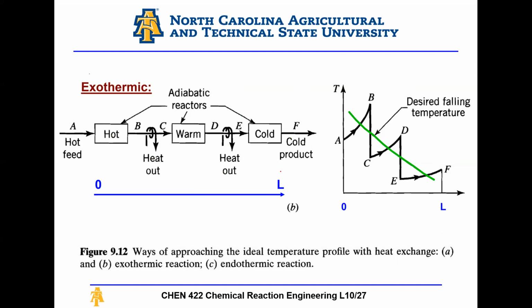A lot of the time you want to do this to minimize risk, for safety issues and for other issues. If you have a toxic gas, or a highly explosive gas, you want to operate using a multi-stage system. This allows you to purge at any point. You never have a huge volume of gas at an extremely high temperature at any point. And you can always purge intermediately. You can always have recycles intermediately. It gives you better control.